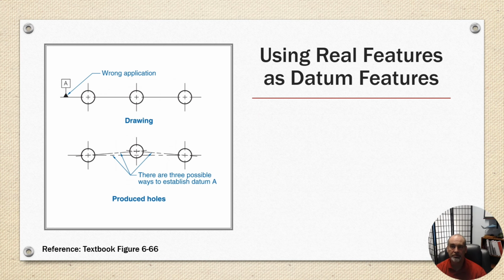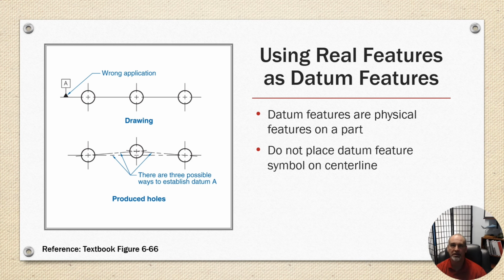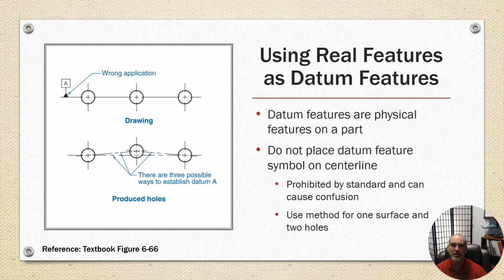Using real features as datum features. Datum features are physical features on the part. Do not place a datum feature symbol on a center line. It's prohibited by the standard. It can cause confusion. Use the method for one surface and two holes instead.